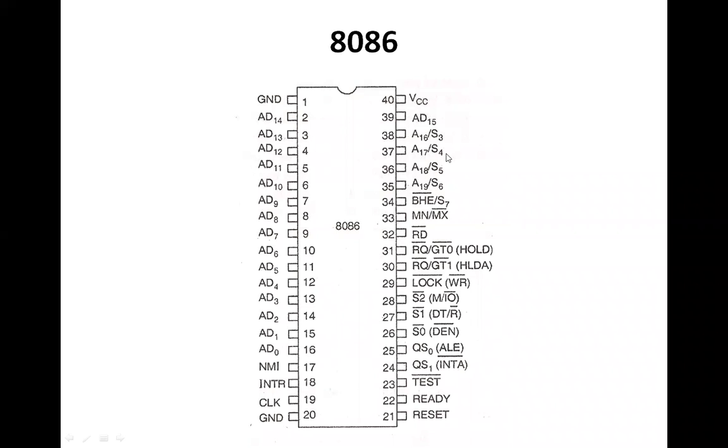So S3 and S4 give the identification of which segment the address is working with, whether it is the data segment, extra segment, code segment, or the stack segment. And the combination of S3 and S4 is going to define that.